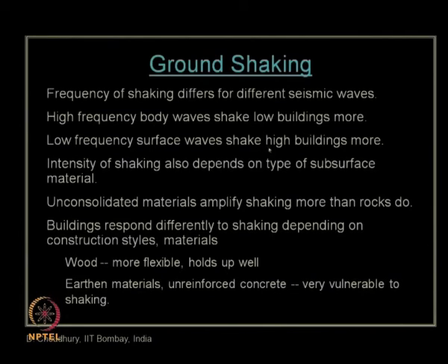As shown here, the correct observation is that it depends on the input frequency of the earthquake. If it is a high frequency, then low rise buildings get more damaged. If it is a low frequency, then tall or high rise buildings get more damaged.